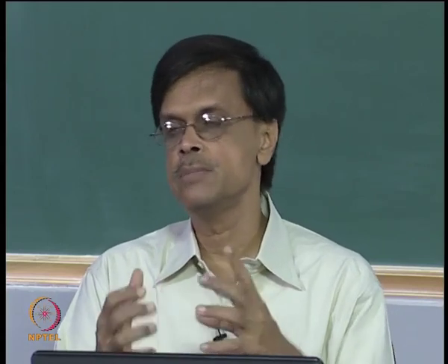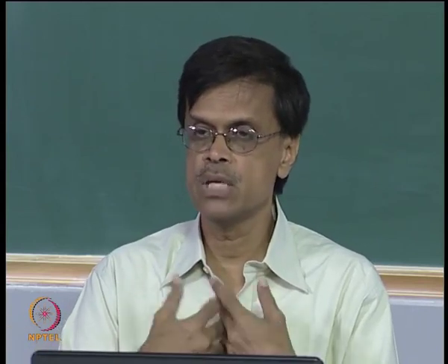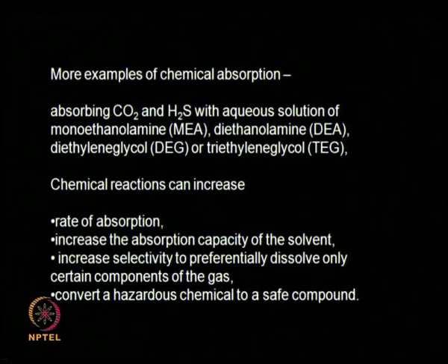So I need to keep on adding. Whereas in physical absorption, the liquid is not consumed, so I can keep on recycling the same liquid. Okay. Whereas in a chemical absorption, I am consuming the liquid, so I need to replace. So if I am using sodium hydroxide to absorb carbon dioxide, I am getting sodium bicarbonate, so I have to keep on adding sodium hydroxide. So it has got a lot of advantages, but there are disadvantages also. So that is called chemical absorption.